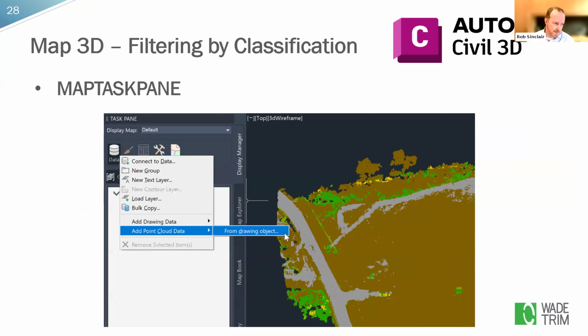One tip that I don't have a slide for: once that surface appears in your drawing, it's automatically going to put you in a 3D wireframe view. And you're going to notice a lot of lagging and slowness when you're trying to pan and zoom, because it has to be in the 3D wireframe view to display the point cloud. But once you have the surface, you don't have to see the point cloud anymore. So you could switch that back to 2D.